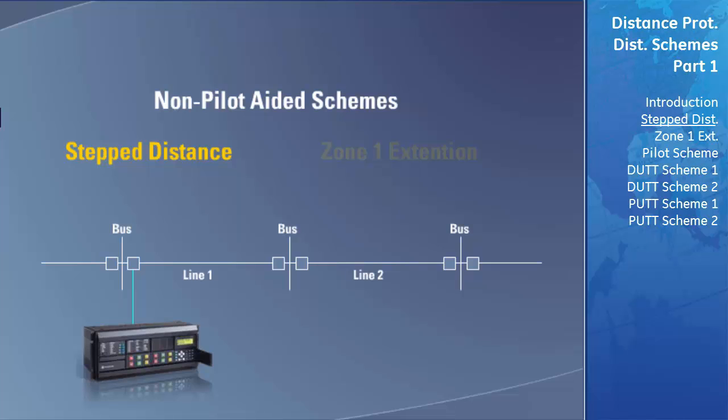The first zone of protection is set to underreaching and extends from the beginning of the transmission line to 80 or 90% of the length of the entire line. This zone is also set to have no time delay. Therefore, if a fault occurs in this zone, the D60 can be sure that the fault is located on its transmission line and can trip immediately.